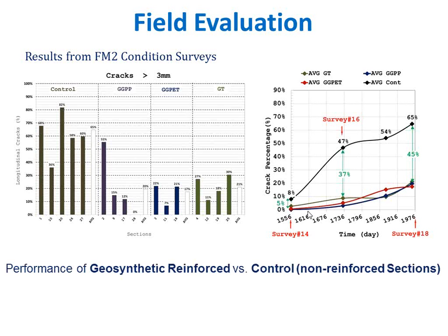This is an entire presentation in itself, but I'm going to tell you why I'm walking you through this quickly. And this is the performance, survey 14, survey 18, crack percentage. Before the dry season, we were at 0% to 8%. Within the span of 12 months or so, the control section went from 8% to 65%. And the reinforced sections unambiguously performed better. It's not that the longitudinal cracks are not going to be present at all. They're going to be minimized, but significantly.